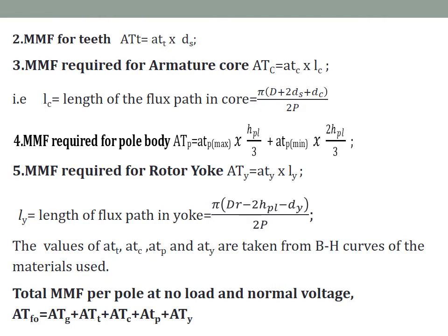Similarly, MMF for teeth, ATt is equal to att into Ds. This is depth of the slot. This att is ampere turn per meter, so this is obtained from the BH curve.